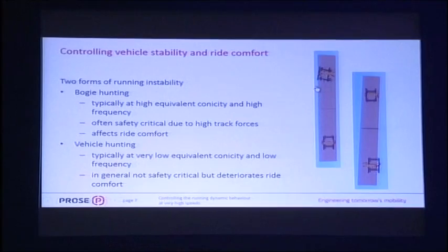And then you have the second vehicle instability. In this case, the bogies remain straight and the vehicle body makes a movement. That occurs at low equivalent conicities and has a very low frequency. It is not safety critical, but it deteriorates the ride comfort.